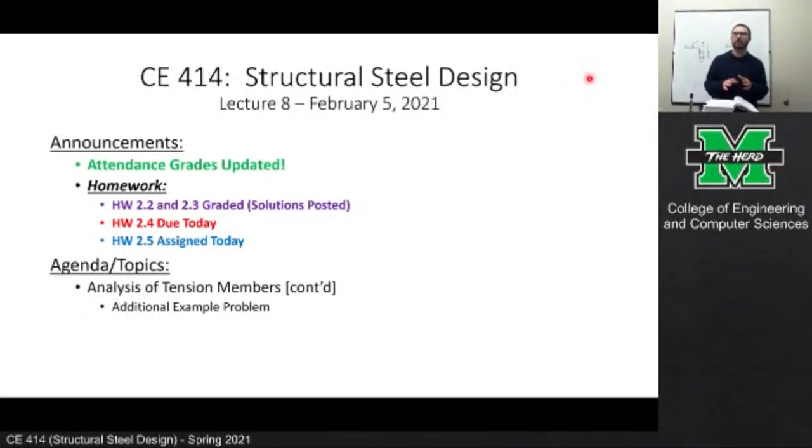Unless... Well, I see what you're saying, and the reason that the manual says that is, and you can even look in table 2-5, you can get different behaviors of strength varying based on thickness. As plates get really, really thick, sometimes the ultimate tensile stress is capped just by the metal structure that you get from a plate that thick, if you look at the structure of the atoms and whatnot.